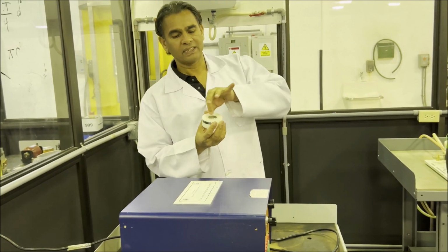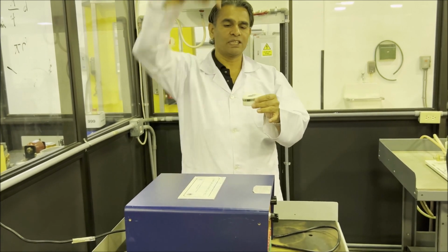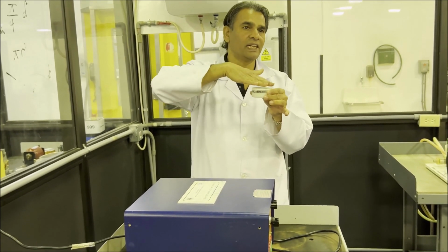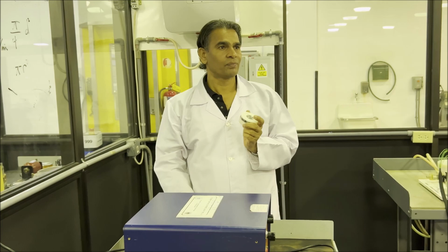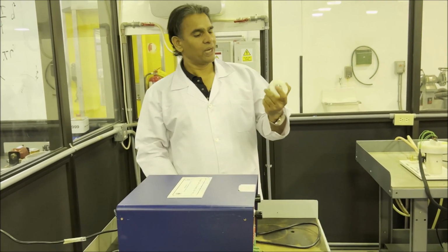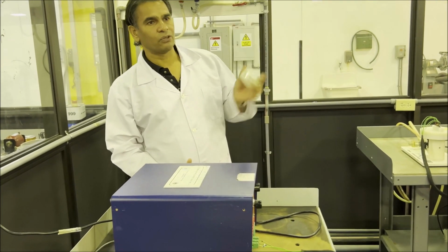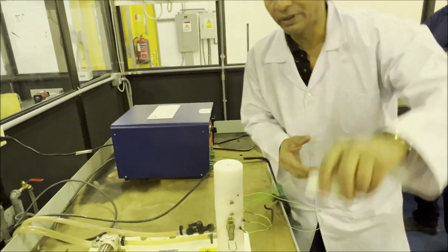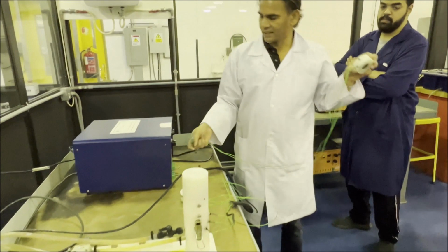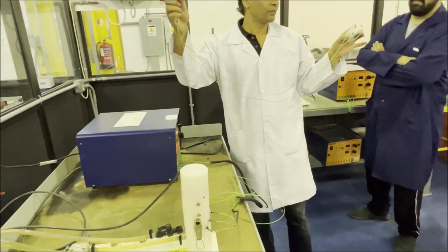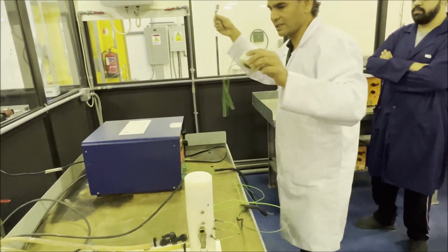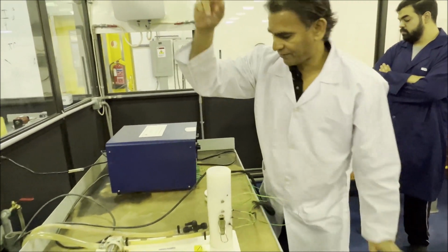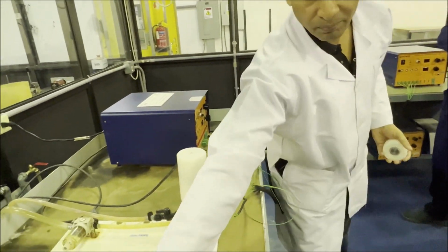The diameter is given to find out the area, because heat is flowing over this cross-sectional area. Now we are going to find the thermal conductivity of this stainless steel. Last week we did this intermediate section, and we took the thermocouple out. Now we are not going to use this; it is only for verification. Now we can use these unknown materials.